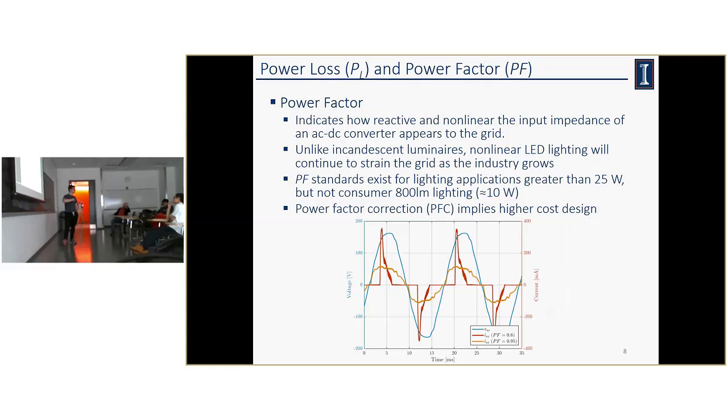Brains that operate slightly differently, maybe. Yeah, but there's no way to shift the phase of the grid. On the DC side, it's very difficult to say where the switching frequency phase will line up. So you might get cancellation there, but you're not canceling the DC side anyway. So yeah, it would not help. Okay. I don't think there's any scheme that would work.